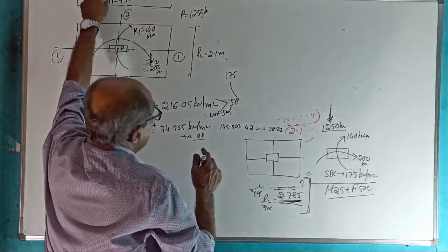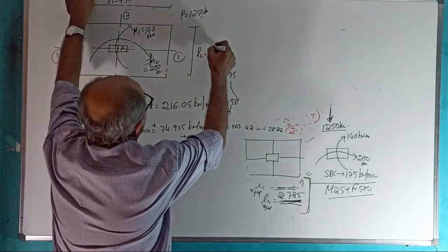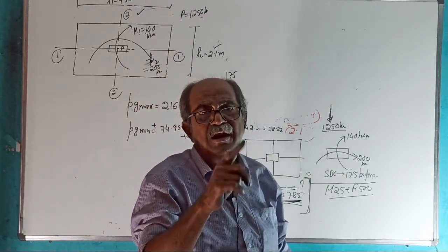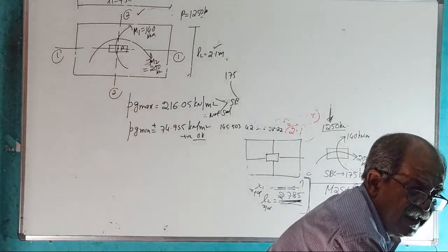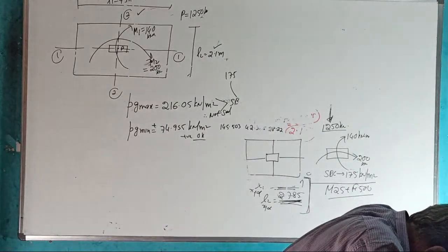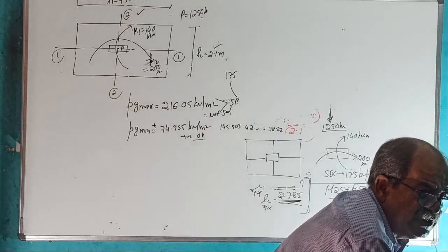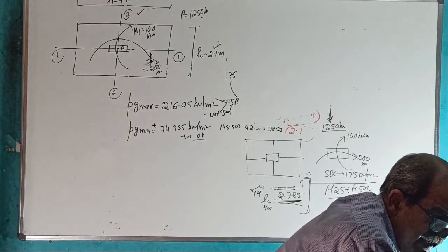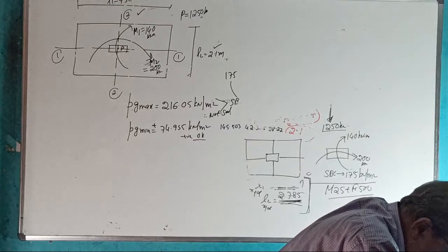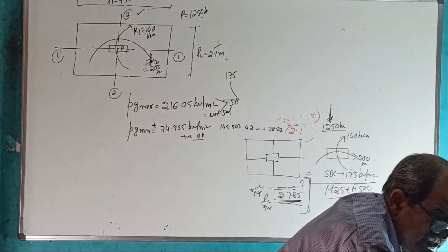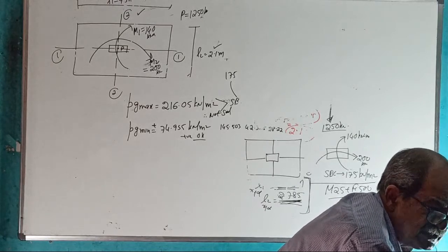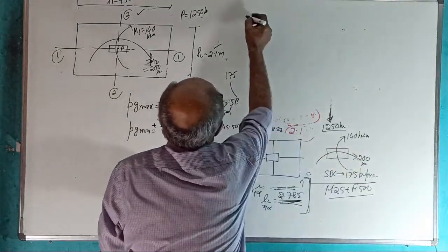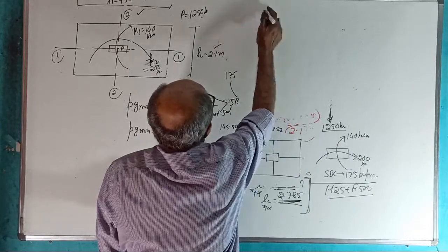Okay. Now, tell me, earlier what we did, we increased both L2 and L1. Tell me yes or no. Earlier we increased both L2 and L1. Yes. But today we cannot increase L2. We can increase only what? Today we can increase only L1. This is going to be a worst case of footing. I have set the question so that one side heavy bending will come. So I will now try L1. Remember, make a note.